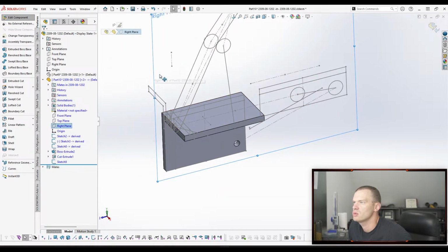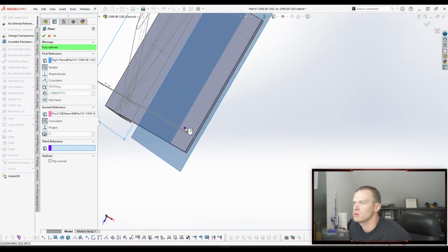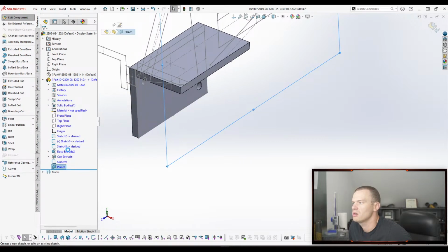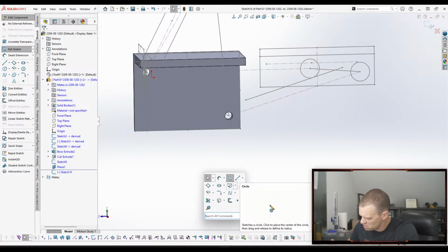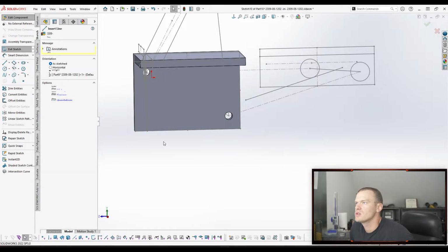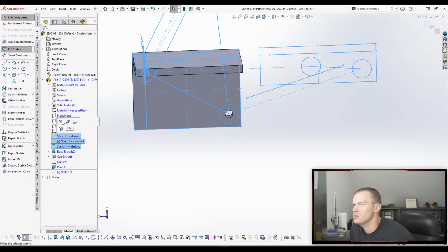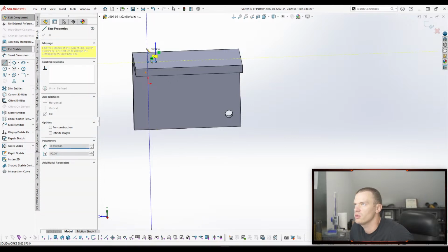So we'll just do something like this, drag this over, and go there. And then we'll just draw in our holes to revolve. Now, normally I'd just do a hole punch, but these are actually holes for flathead screws. So we'll hide this stuff here for now. And we'll draw our profile that we're going to revolve.